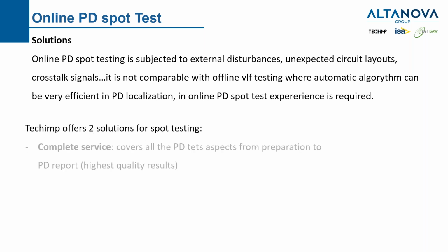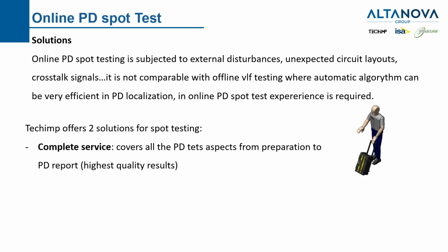What is the solution Techimp offers? We offer the complete service. So somebody requests from me or my colleagues a survey on this cable. We ask for the cable specification, we ask for layouts and so on. We evaluate the chance to make the test, if it is a good test, I mean, if we can be sensitive when testing that cable. We provide a test procedure. We go on site, we take the measurement, we analyze the data, and we provide the result.